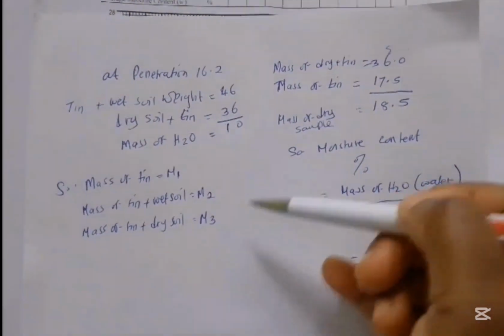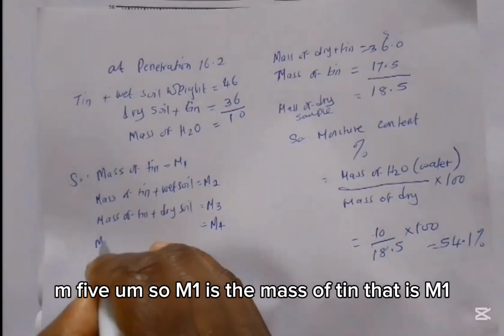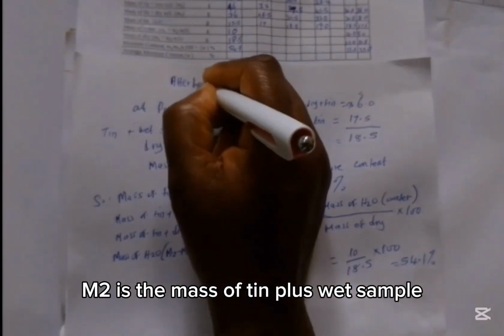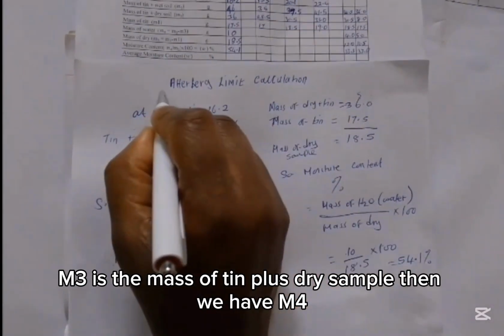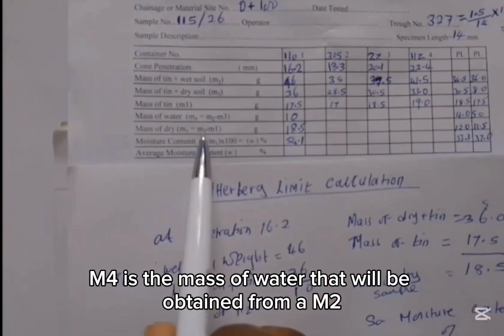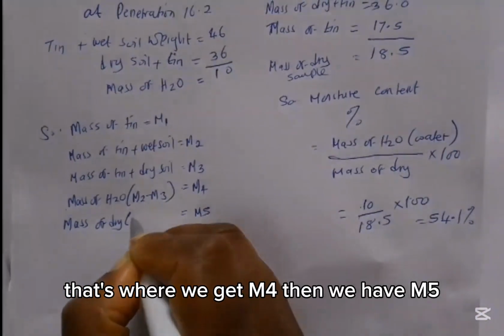So when we calculate we use M1, M2, M3, M4, M5. M1 is the mass of tin. M2 is the mass of tin plus wet sample. M3 is the mass of tin plus dry sample. Then we have M4. M4 is the mass of water that will be obtained from M2. So that is, water is wet weight minus dry weight. That's where we get M4.